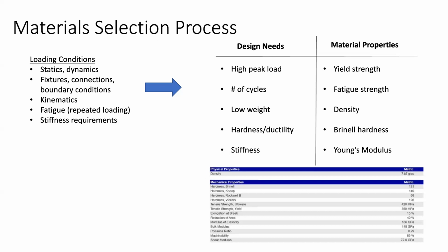And you can get a little more complicated with this in terms of if you have a shaft, which is supporting a pretty large moment load, you need a relatively high hardness. So then you would look to something like the Brinell hardness. So we're going to be going through each of these properties at a high level, just talking about what you need to look at, not necessarily all the theory behind it. But I just really want to drive home the fact that you should always start with the requirements, and very naturally the materials requirements that you need kind of fall out of that.